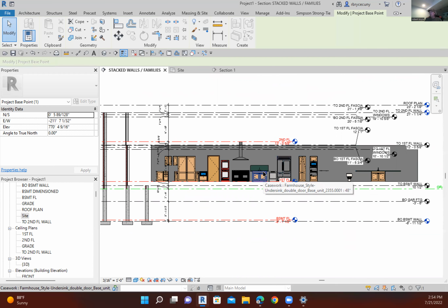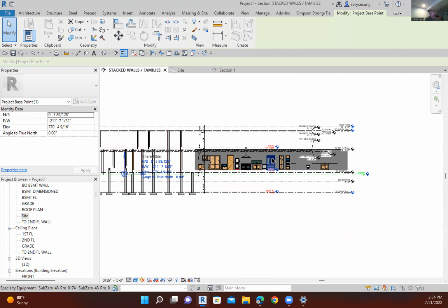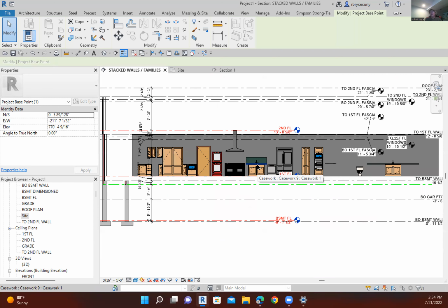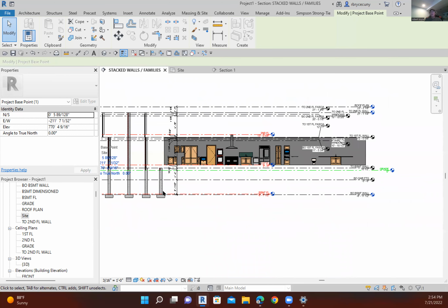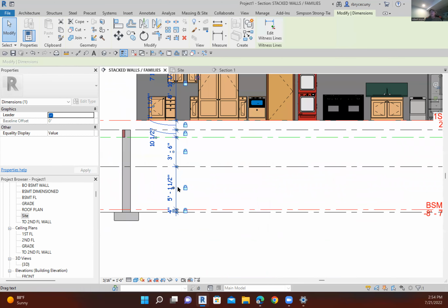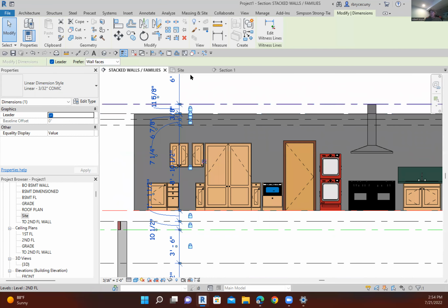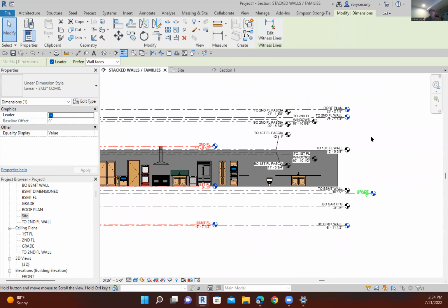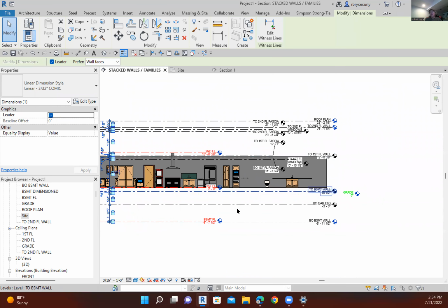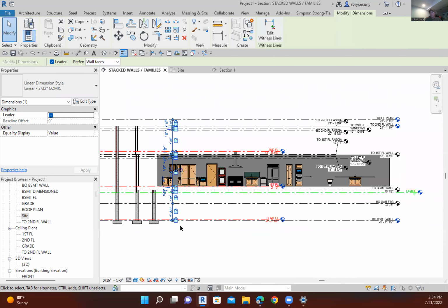But it's possible that you've started your house design prior to receiving the actual elevation that you need to set the house at. So simply put some dimensions in to make sure that they're all locked together. And so then when you move one of these elevations, these levels, all of the other levels move as you wanted them to be, distance-wise apart.